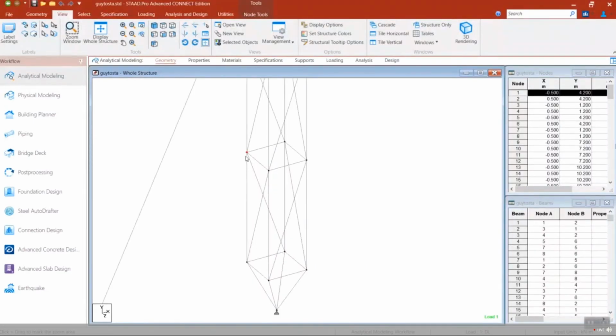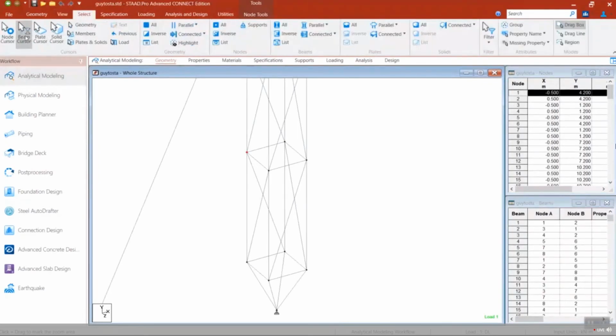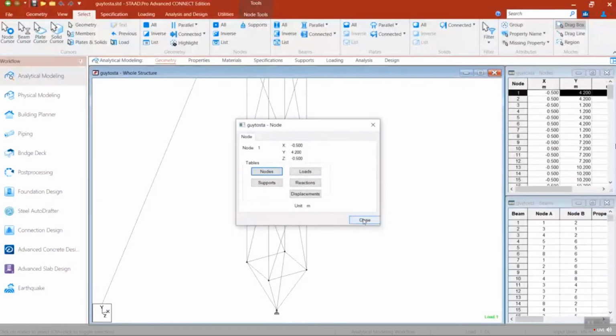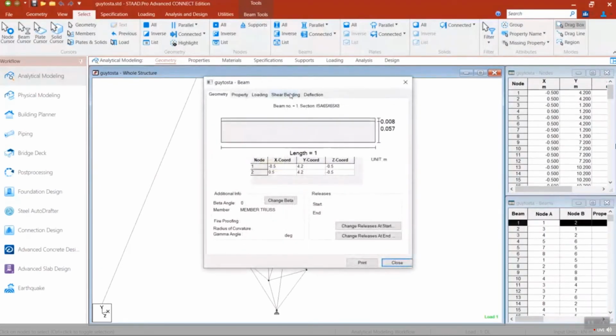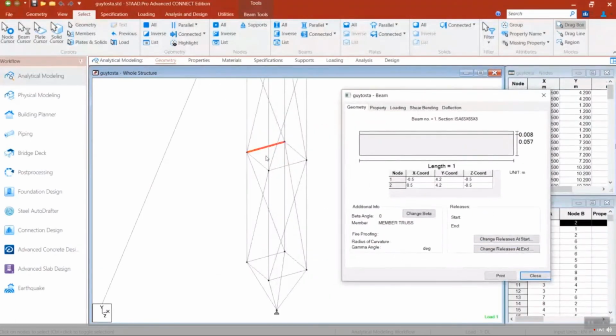You usually get a zero stiffness in the direction of 4, 5, and 6. 4 being MX, 5 being MY, and 6 being MZ. So you can see this highlighted point, all the members are truss members. So there you definitely get a zero stiffness warning message.